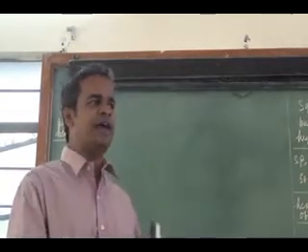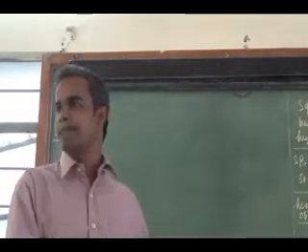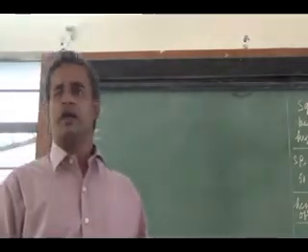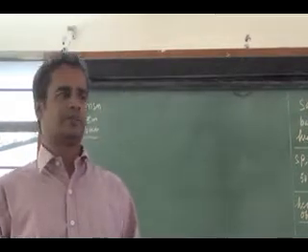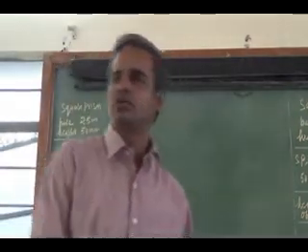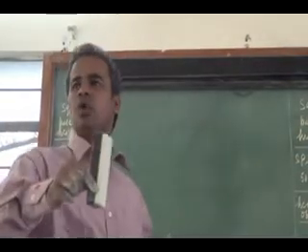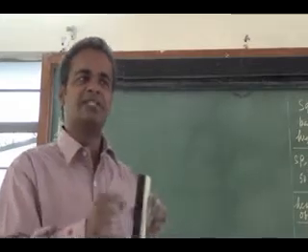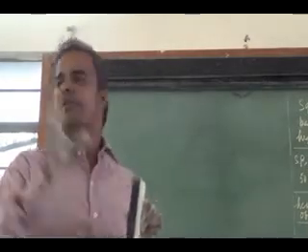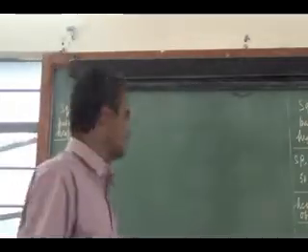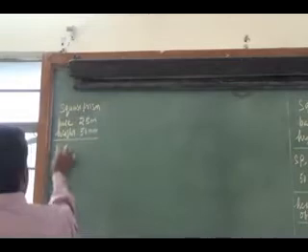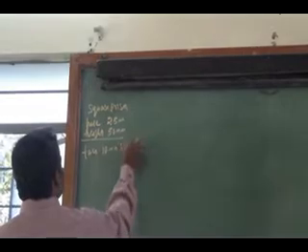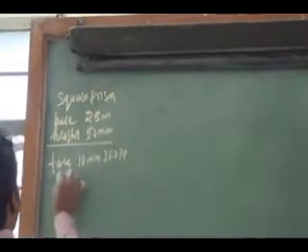Remember, see carefully. The face is parallel to the picture plane, and 10 mm in front of it. You see here, the whole object is not in front of the picture plane. What is in front? The face which is parallel. That face alone is 10 mm in front of the picture plane.